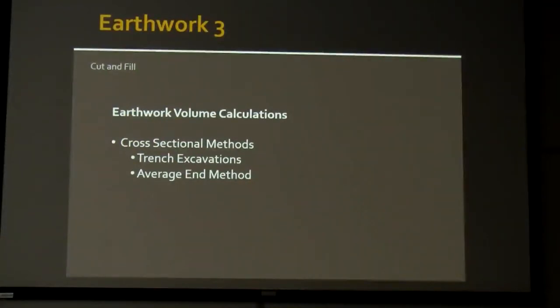Also, it's going to determine how many truckloads we're going to need, how many trucks you will need to haul the material, and to be sure that we have a continuous balance, so that we always have a truck ready when we're ready to dump the excavation from our front end loader, from our equipment on the field, and put it into the trucks. At the same time, we don't want to have a lot of trucks waiting and sitting, because that hinders our production rate. So we want a nice balance between the earthwork volume that we're removing and the truckload volumes that can be used to carry it away.